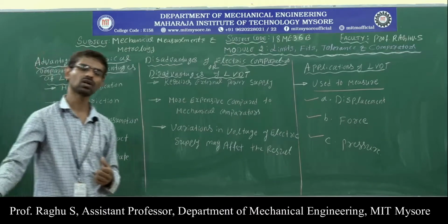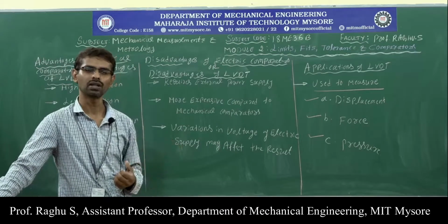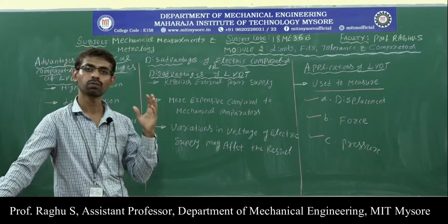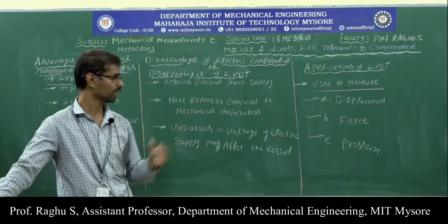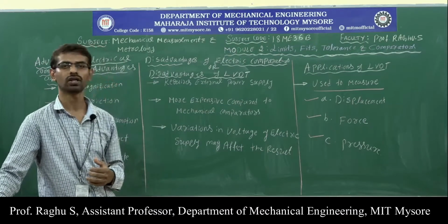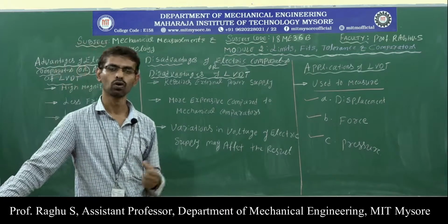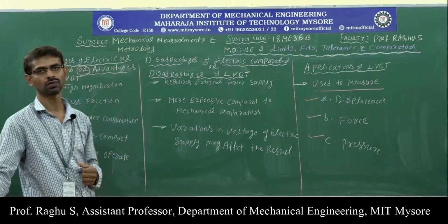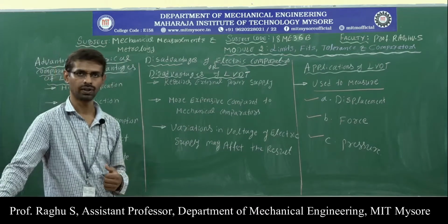And coming to applications of LVDT, LVDTs are mainly used to measure mechanical displacement in the range of fractions of millimeters to centimeters, and LVDT is also used to measure pressure, force, weight, etc. So these are some advantages and disadvantages of electrical comparators or LVDT.